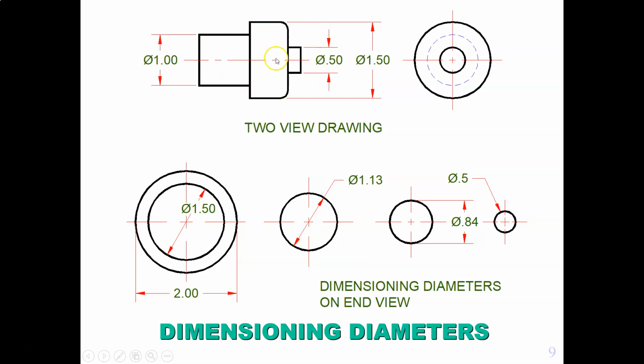These are all given where they are rectangle shapes. We don't ever point at them where we see them as circles. So here, if you notice, what we've got is a 1.5 inch diameter, but then here we've got a circle out here. We should not give this here. If this is a cylinder, that number should be given where we see it as a rectangle.